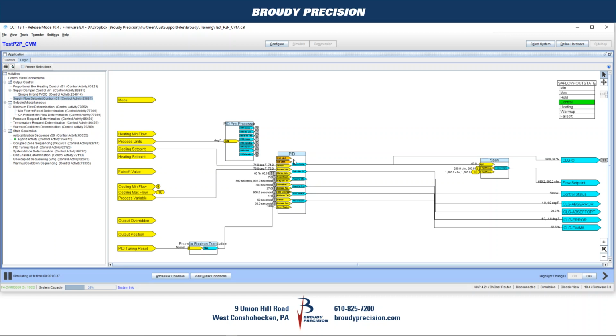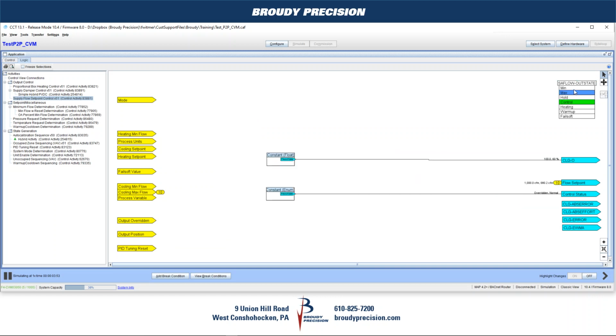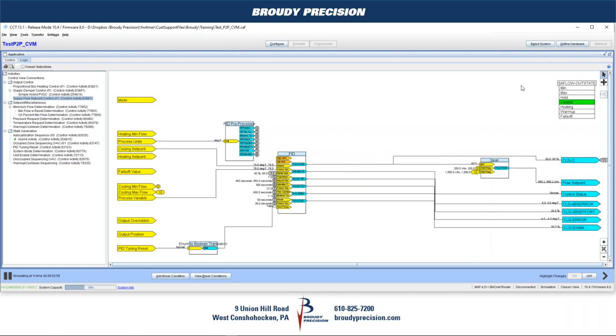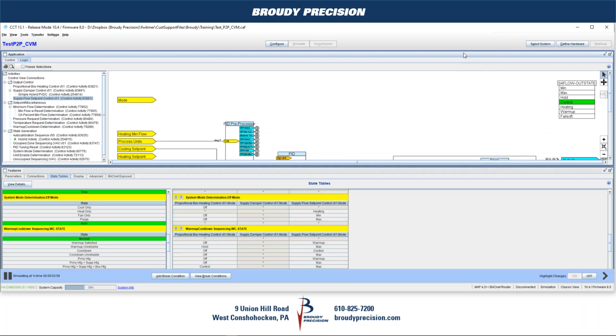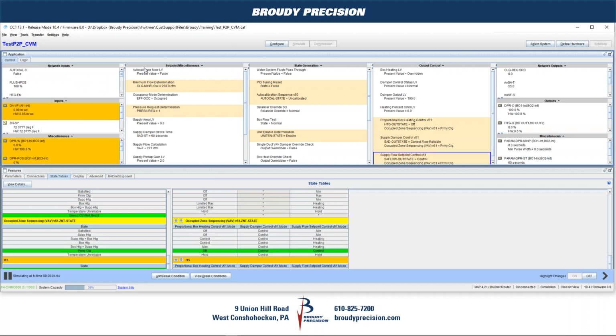And the way that works in here with the state-based control is, as long as the mode is control, PID is in operation. If you go out of that mode, it actually gets turned off, so you don't get windup of the integral control of the PID. And we can go back and look at our control again.